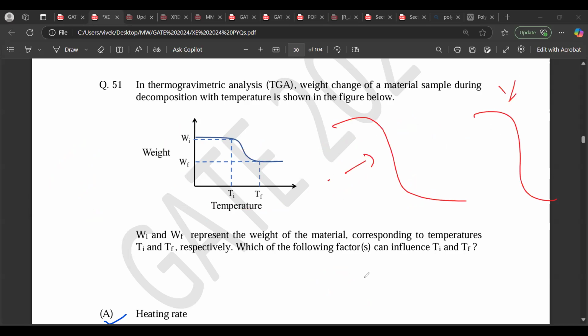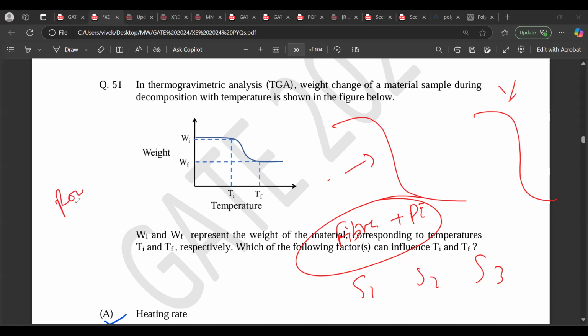Let's say you have made three samples, S1, S2, S3, by adding some composition. Let's say you have added fibers in your polyethylene, so you made a composite. Now you want to do DSC, and you're testing it in a DSC, or any kind of machine, even the UTM machine. You have to know what factors you have to keep the same, like room temperature. You have to test at room temperature or the same temperature.